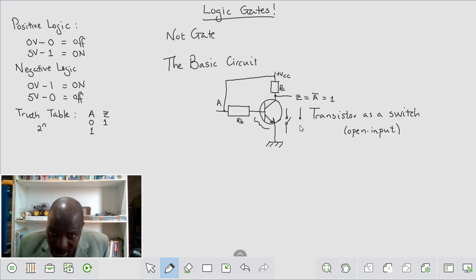When the transistor is saturated, it basically behaves like a closed switch. So the two possibilities for this transistor are open circuit when there's no sufficient biasing, or saturation where it behaves like a closed wire. If this was a closed path, like a wire, then you can see that ground is now connected directly to the output. Ground is 0 potential. We can't have it now being a 1, because it's not the potential of ground. It is therefore going to be a 0.